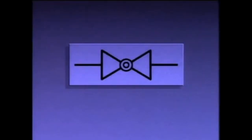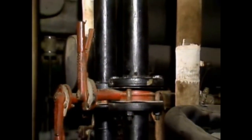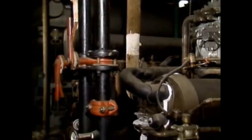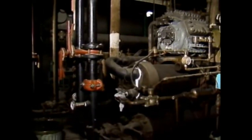On a piping system diagram, a ball valve symbol generally looks like this. If the symbol looks like this or has the letters NO beside it, then the valve is normally open in the piping system. If the symbol is filled in or has the letters NC beside it, then the valve is normally closed. Butterfly valves are used for a variety of purposes in industrial plants. Typically, butterfly valves have round, relatively thin valve bodies. Because of this, they take up a lot less space in piping than many other types of valves.